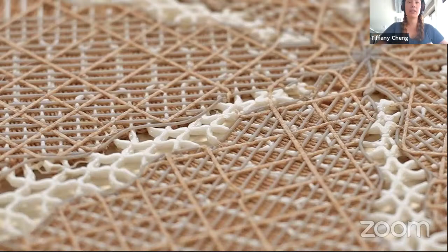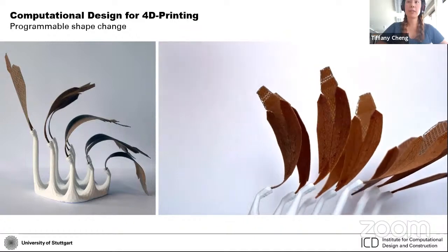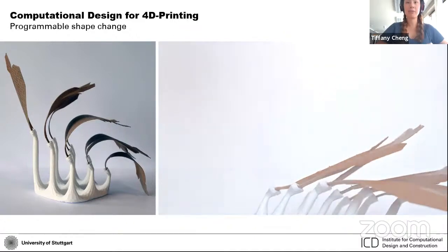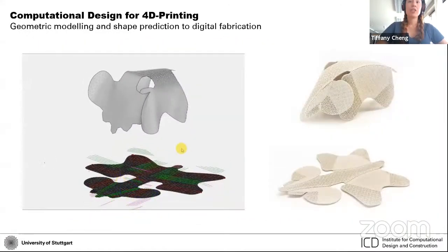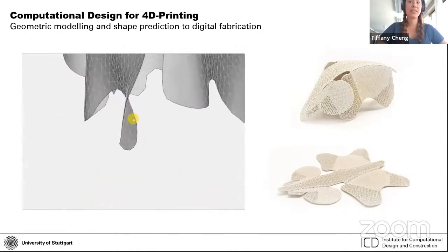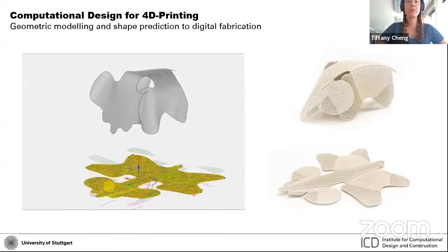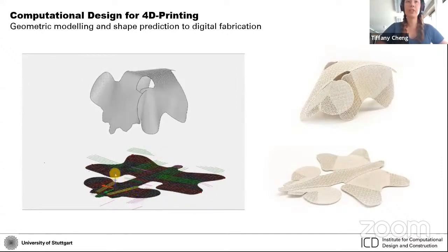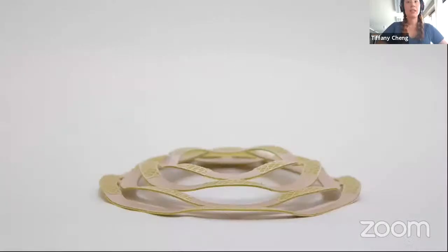This allows us to create parts with programmable properties, bending directions, timing, and sequence. To do this, we also developed complementary computational tools for programming these varieties of shape changes. It's interactive and lets us quickly visualize the shape change, and the result can be directly 3D printed. We'll also introduce some of these digital techniques in several tutorials throughout the workshop.